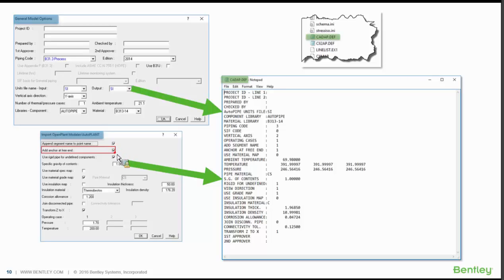So just play around with these options, whether you want the anchors. Maybe you want them at most points, but not every free end. So you just go into your model and delete the couple of anchors that you don't want in there. After importing, you always want to check your model thoroughly and make sure that everything looks good. So use these options to help you out. Each model would want this dialog box set up differently according to how we want that model imported.